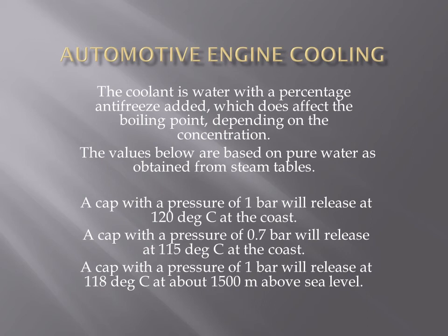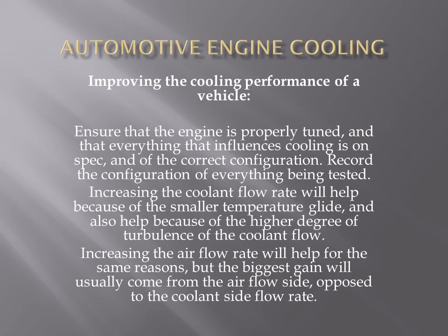Coolant in water is water with a percentage antifreeze added, which does affect the boiling point, depending on the concentration. The values below are based purely on pure water as obtained from steam tables. A cap with a pressure of 1 bar will release at 120 degrees centigrade at the coast. A cap with a pressure of 0.7 bar will release at 115 degrees at the coast. A cap with a pressure of 1 bar will release at 118 degrees centigrade at about 1,500 meters above sea level.